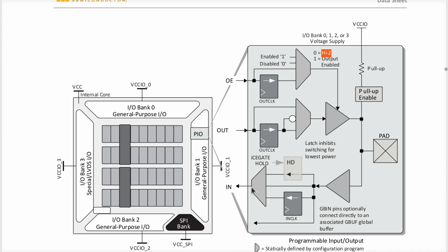It's going to flow through this MUX and into the routing network and LUTs and wherever it's going to go in the design that I've created, okay? So if we don't have a pull-up resistor and this thing floats, it will chatter. Very high frequency noise will come in on here. And it'll actually look like the LED is getting bright and dim, because it'll be oscillating on and off because this pad is floating, and this gate here will be going hello, hello, hello, depending on what the circuit is doing with this pin, okay?